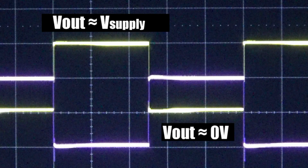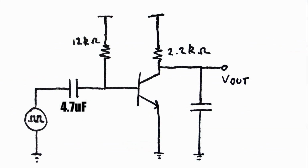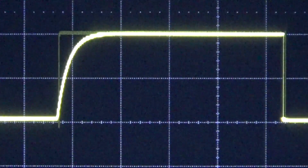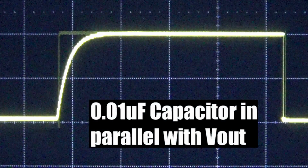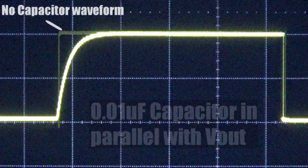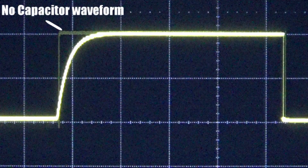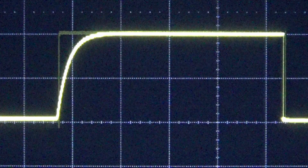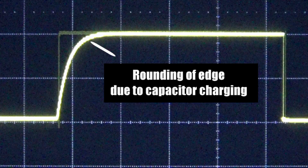Let's add the capacitor back into the circuit and see how it behaves. Here's the output with a 0.01 microfarad capacitor plugged in parallel with the output. I used the persist feature of my oscilloscope to keep previous acquisitions on the screen, so we can see what it looks like with the square wave output with no capacitor and with the capacitor plugged in. Notice how the edge of the square wave starts to round off. This is due to the capacitor charging up.